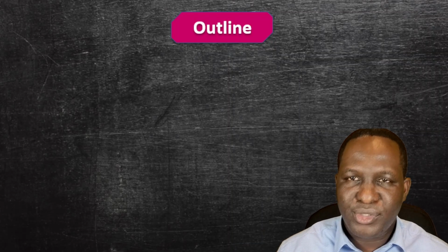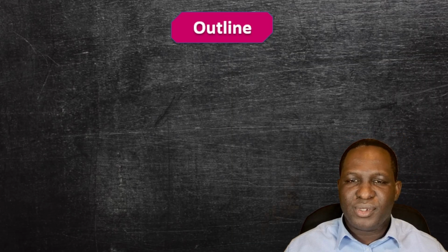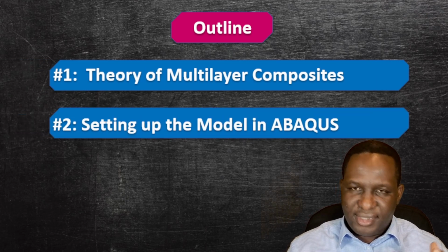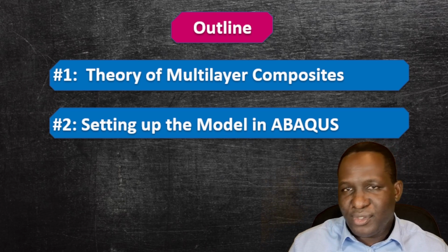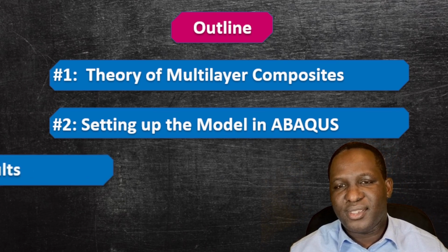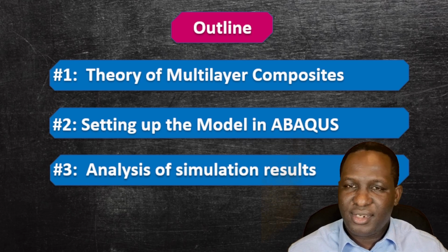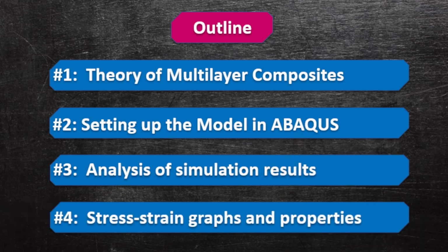So the outline that we're going to work with in this video is that we're going to show you the theory behind multi-layer composites and setting up of the model within ABAQUS, so that at least you get a sense of how to do this for yourself. And then we'll show the analysis of the simulation of the results generated from this, and finally show you also how to generate stress strain graphs and effective properties from this type of composites.